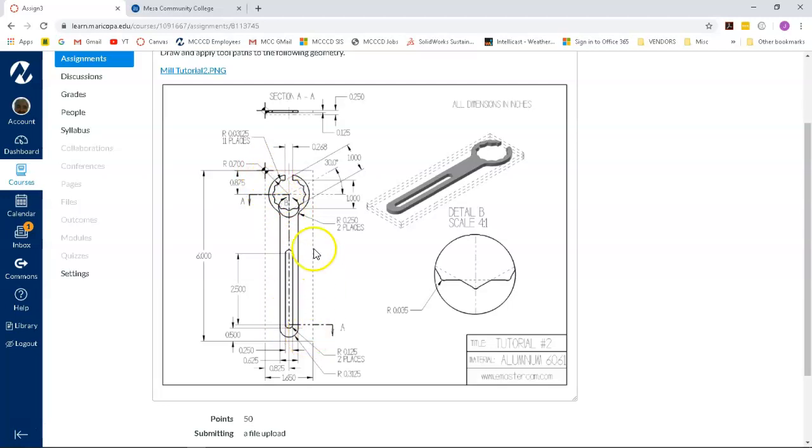I don't know of any vises that I would put a 1/4 inch piece of material in and open it 6 inches and hold it in this orientation. I would rather let it chatter on the narrow side instead of the thick side. So previous times I've done this with the intent of having a clamping, that universal tooling plate that we would clamp this down and find some method, either run the slot and make a fixture that had a couple holes in it that would center on the slot that we could bolt down, bolt in the center.